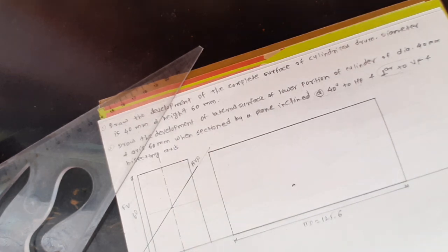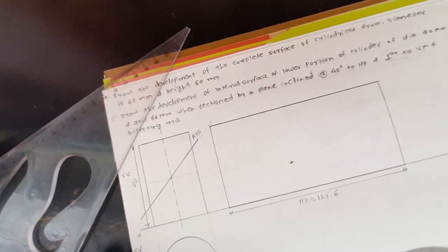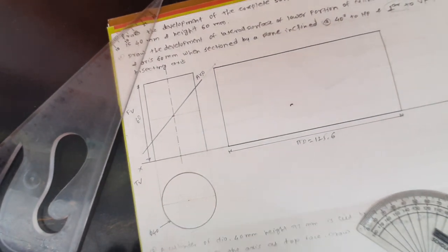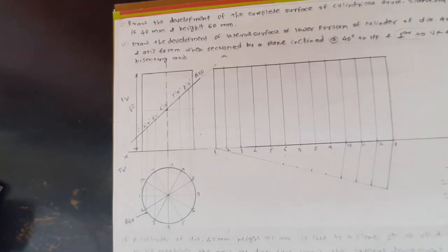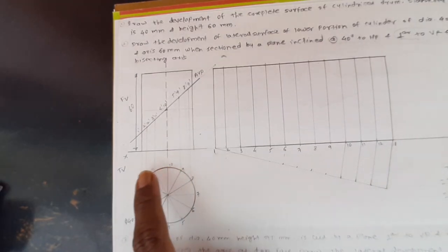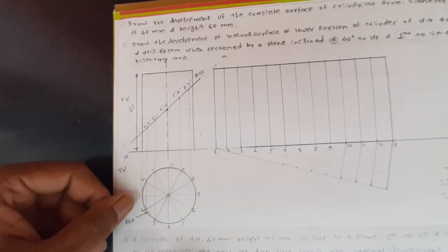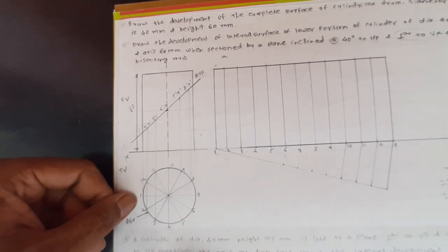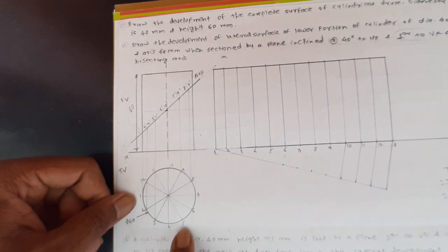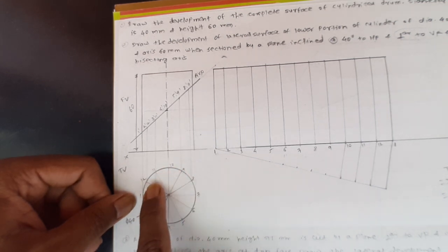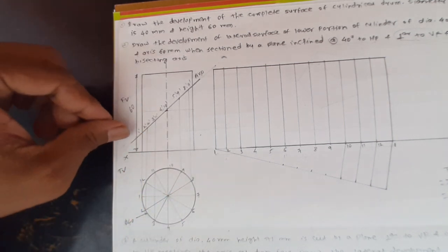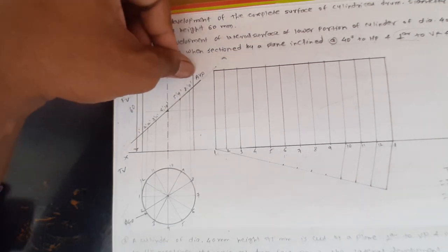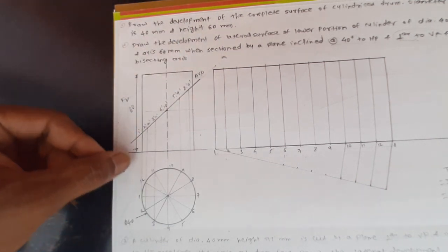cylinder vertically. Now for this, what we are doing, we are dividing this circle into 12 equal parts and taking the projection in the upward direction. Here I divide the circle into 12 equal angular parts. So write the numbers from the left side: 1, 2, 3, 4, 5, 6, 7, 8, 9, 10, 11 and 12. Now take the projection of all these divided parts up to this inclined auxiliary vertical plane. Now mark these notations over here.